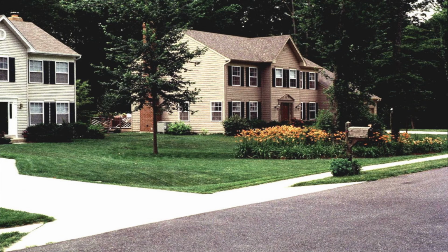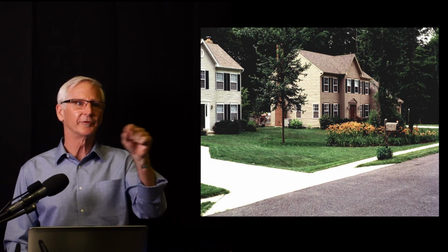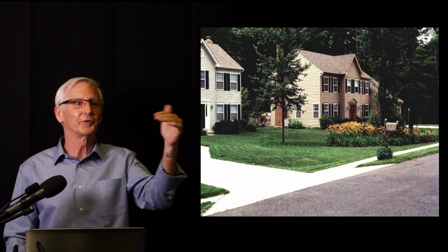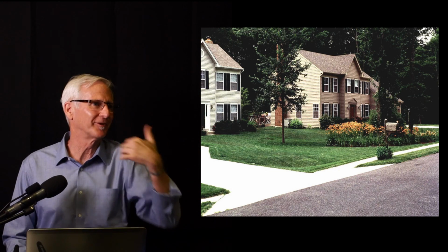This offline, online approach, this is an old shot. This is one of the first bioretention areas built in the US, back on the East Coast. It's a little hard to see, but right along the road there's a swale, a gentle swale. And where those yellow flowers are planted, that's the bioretention area. The inlet is off the swale, and the inlet is the same as the outlet, right? So that's the control. Water flows to a certain level, and then it starts to back flow out.